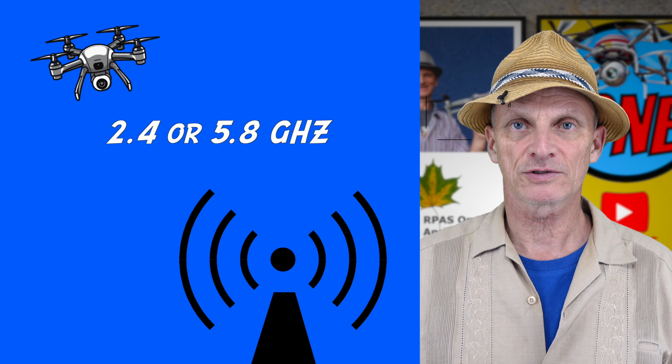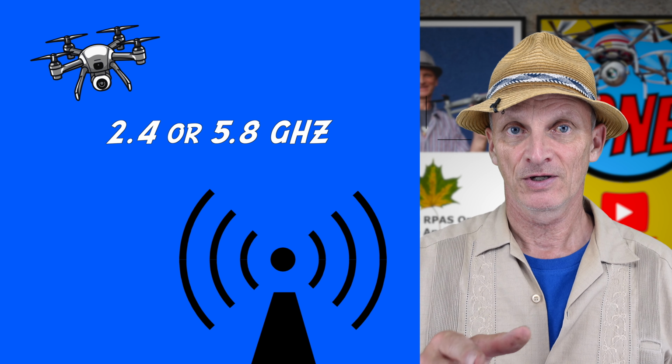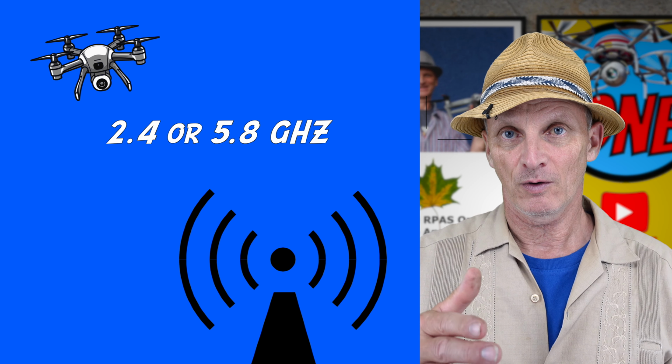What about flight control and communications? Well, you control your drone using a ground station. This could be a remote controller, a smartphone or tablet running an app, or a combination of both. The controller sends radio signals to the drone, usually in the 2.4 or 5.8 gigahertz bands. These signals are affected by obstacles, interference, distance, and something called the Fresnel zone, where even nearby objects can cause disruptions. Many drones, like the DJI models, scan for interference and automatically switch channels.